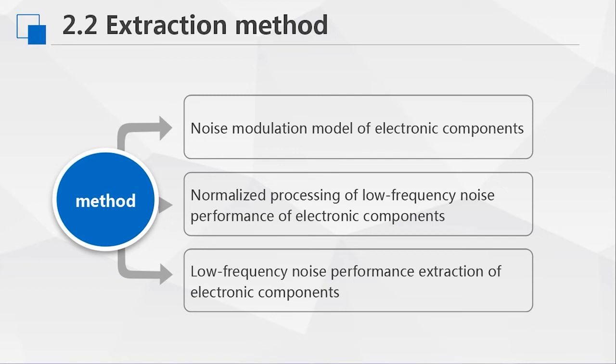By synergizing the low-frequency noise and intensity of electronic components, a simple model that can produce stochastic resonance is obtained. Based on the calculation result of the signal-to-noise ratio, several low-frequency noise components are removed to ensure that the remaining low-frequency noise performance is significant, which is equivalent to filtering by a high-pass filter. The filter bank is completely adaptive.